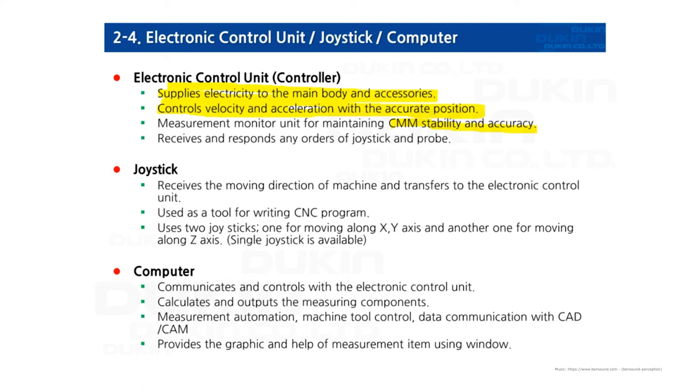On the right side of the LCD, there is a lever to control the machine's speed in CNC mode. And there are lock keys for each axis on the side, and the touch disabled reset button is located next to the emergency button. If you press the touch disabled reset button when the CMM is normal, it cuts off the signal through the probe sensor. And if you press the button when the error message is on, it will clear the message if the error is already solved.